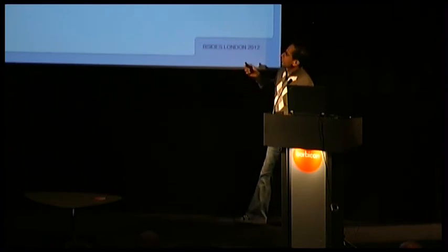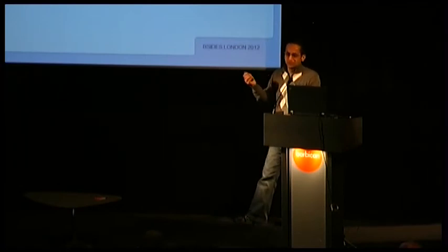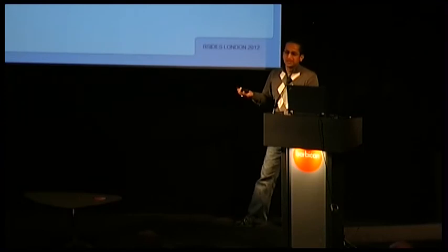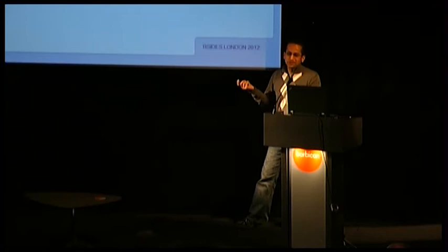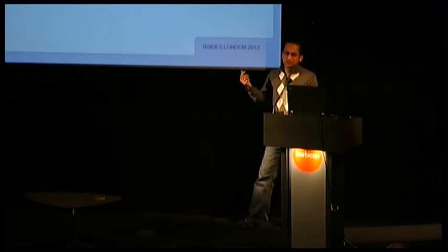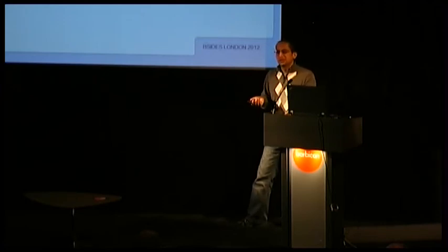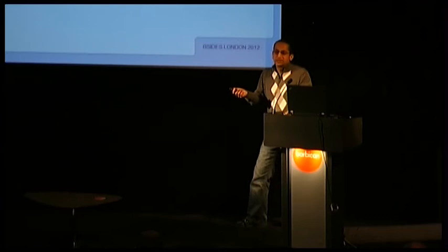What the Modbus frame consists of is a Modbus header. Usually most protocols have some sort of a protocol header. It has a function code and it has data. The header consists of 4 parts. It has a transaction ID, which is 2 bytes. A transaction ID is basically to identify the transaction.